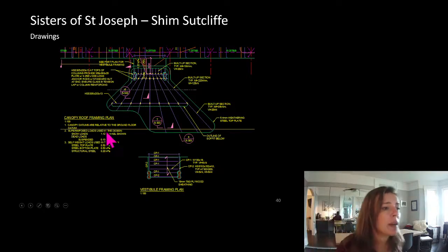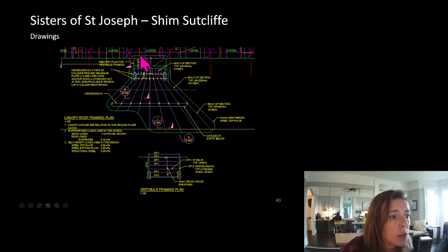So on this one, I say 1.12 kPa plus ASL shown. Well, look at this. Here's my ASL, or my accumulated snow loads. The drop off onto snow loads here wasn't that great. This was also an older code where the way they calculated ASL was slightly different.